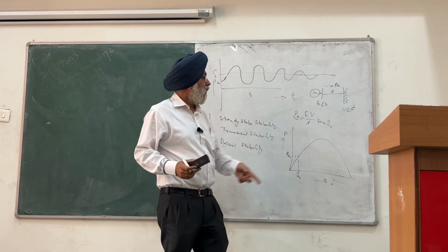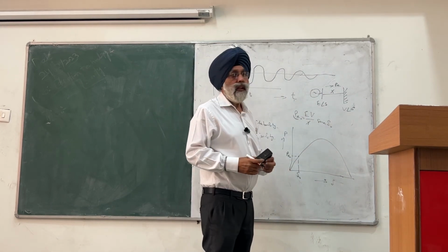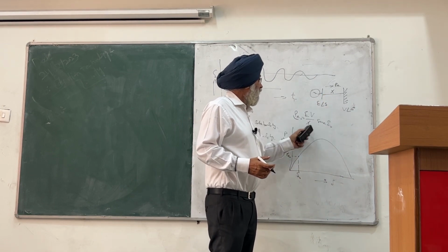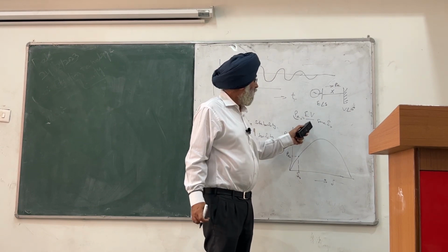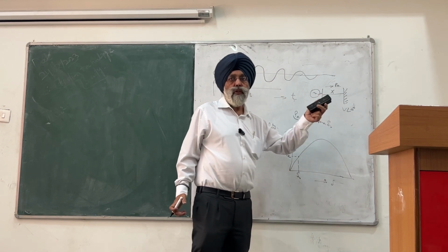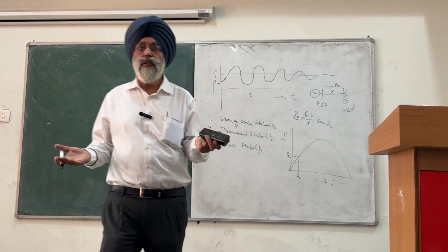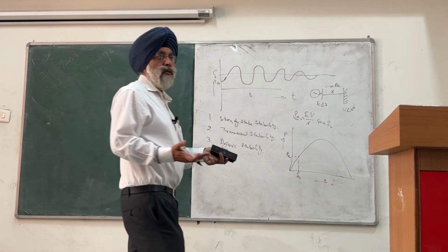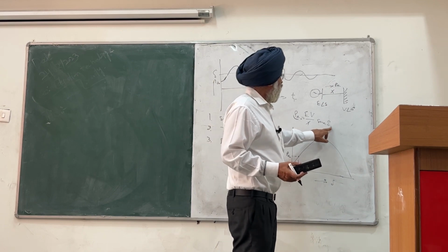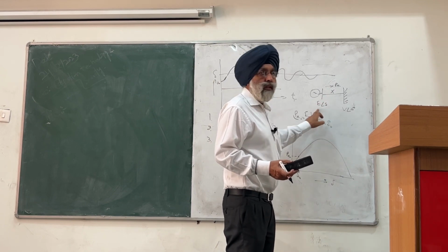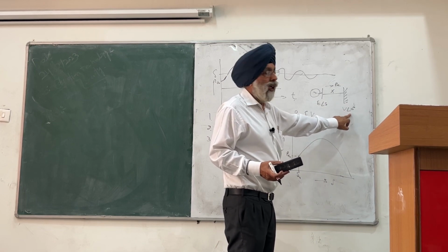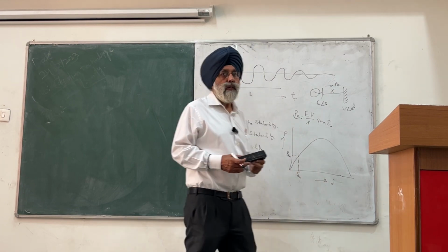So then the electrical power PE is given by this equation, EV by X sine delta. E is the voltage level here, V is the voltage level here, X is the reactance, or we can say the impedance, where out of the impedance we have neglected the resistance. Our line, our conductor, mostly has reactance. That is why we have taken the reactance here. And sine delta means the initial angle difference between the voltage V and E, that is delta 0.